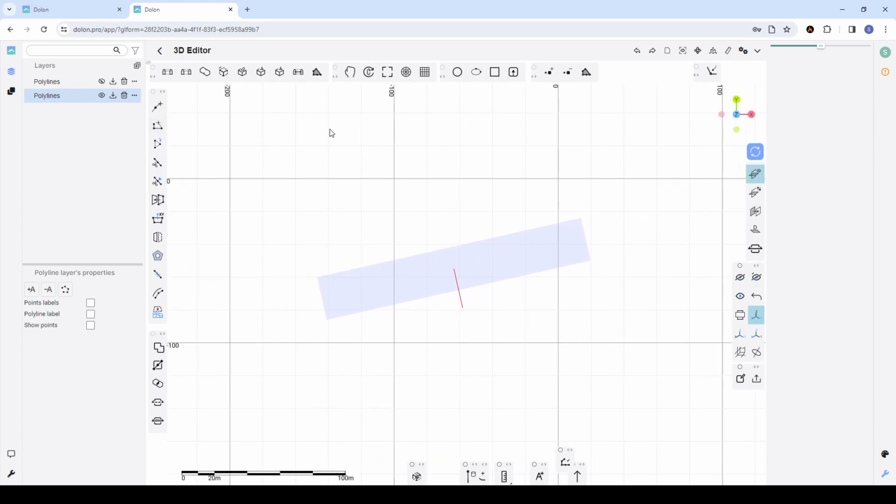Sometimes we need to create polylines or predefined shapes, and we know the coordinates, and according to those coordinates we need to create some lines or zigzags or other stuff. In this case we can use dynamic input. First of all, dynamic input helps to set certain coordinates automatically.